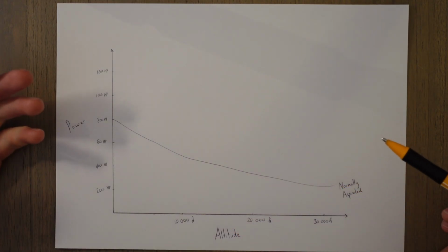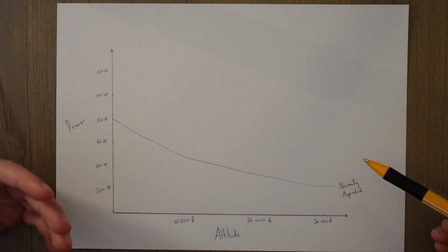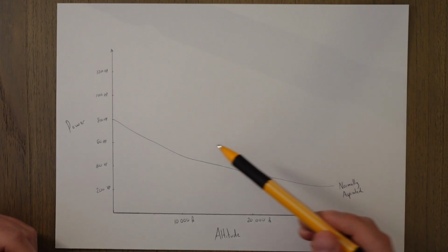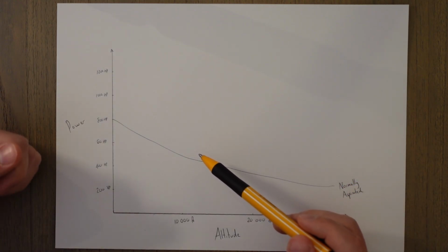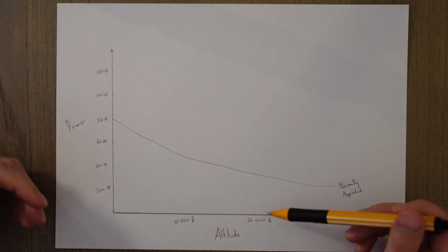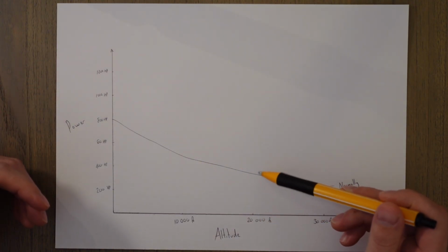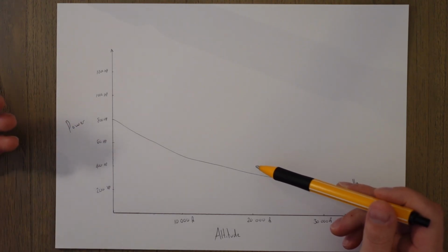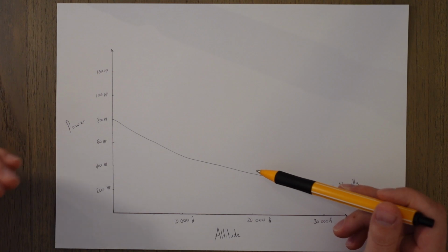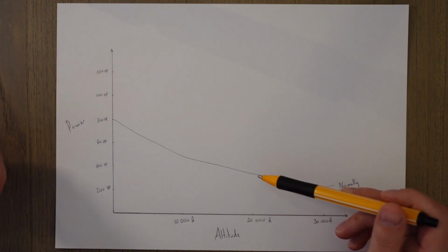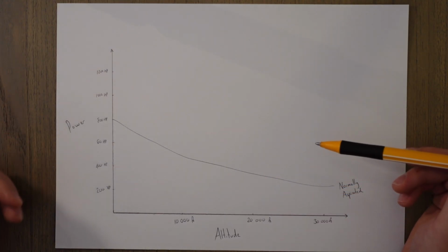To counteract this, you can open the throttle more, allowing more air and more fuel into the cylinder as you climb. There does, however, reach a point where you're at full throttle and you can't let in any more air and fuel into the cylinder. For example, at about 20,000 feet, a normally aspirated engine will have lost about 40 to 50% of its power. You see I said normally aspirated there, which means it's just getting the air drawn in without the use of something called a supercharger. So what is a supercharger then?